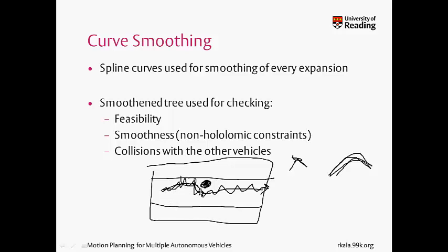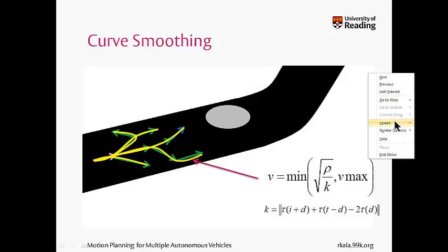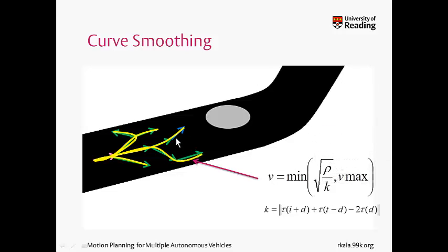Maybe what the controller does is to trace in this trajectory where here the vehicle might collide. So I need to be assured that the trajectory is smooth as well as obstacle free, and that will be the next challenge. And this is what we call the smoothened RRT, or the RRT with all smoothed edges. What I've done is very simple. It's the same old RRT that we saw in the previous slide.